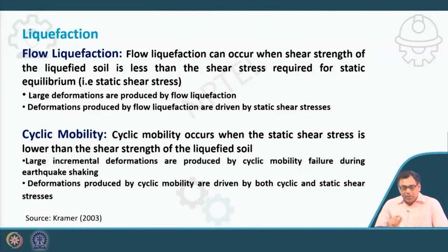So large deformations are produced by flow liquefaction, and the deformation produced by flow liquefaction is driven by the static shear stress only.